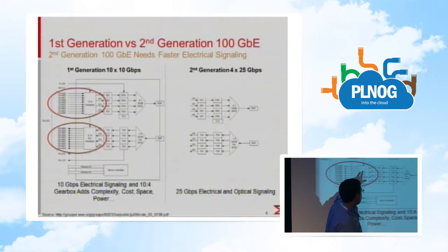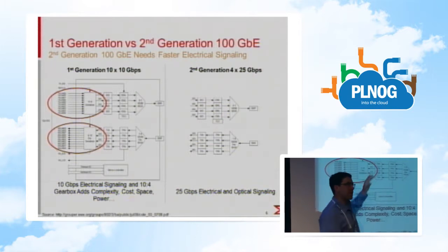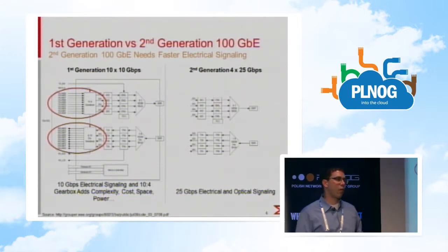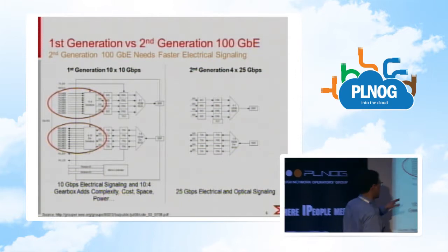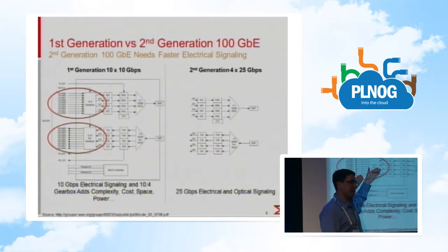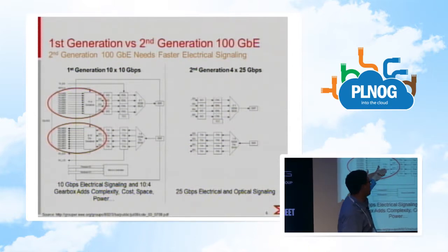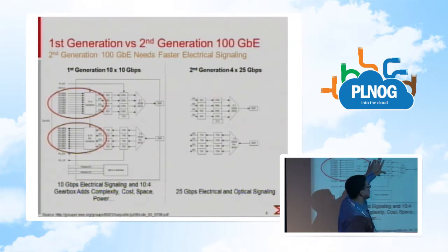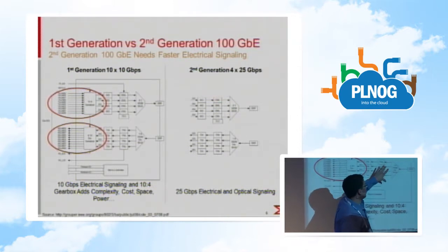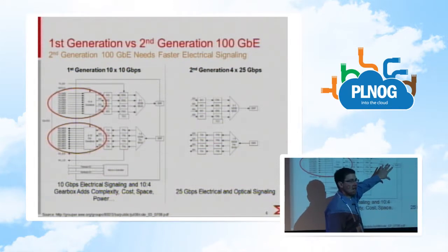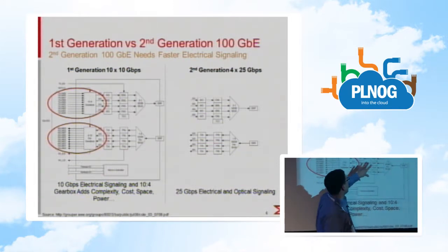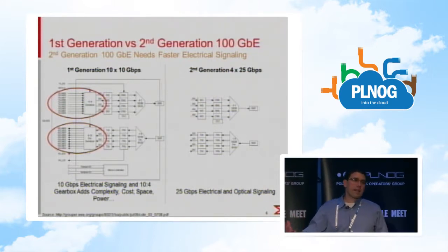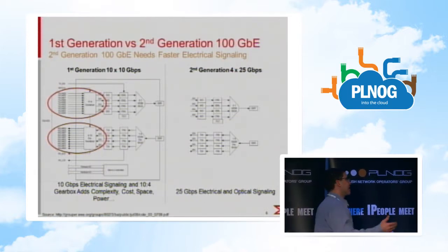Inside that optical module is then a converter that converts that 10 by 10 electrical signaling into a 4 by 25 electrical signaling. So this is an ASIC. It's simply a chip, a serializer/deserializer, that converts one parallel interface to another parallel interface, which then drives a number of photodiodes or lasers to signal optically out of the SFP or the optical module. At the bottom, it works in reverse the same way, driving the inputs that come in at 4 by 25, turning it into 10 by 10.